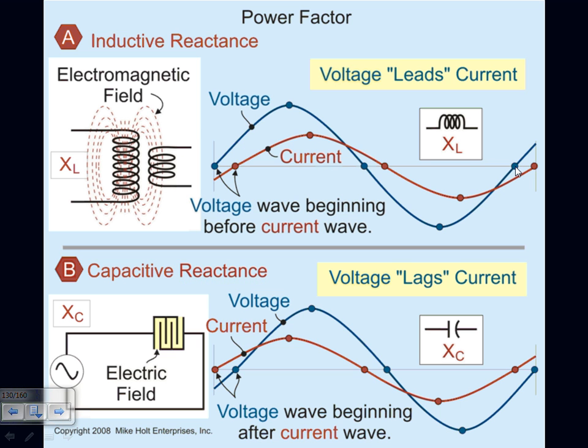If you had 105% power factor through excessive capacitance, would you have to add inductance to the circuit? In a low voltage system, 600 or less, that will be my last option. If you're medium voltage, yes. If you're doing transmission distribution, medium voltage, yes. In low voltage 600 or less, my first option would be to reduce the amount of capacitance that I have.